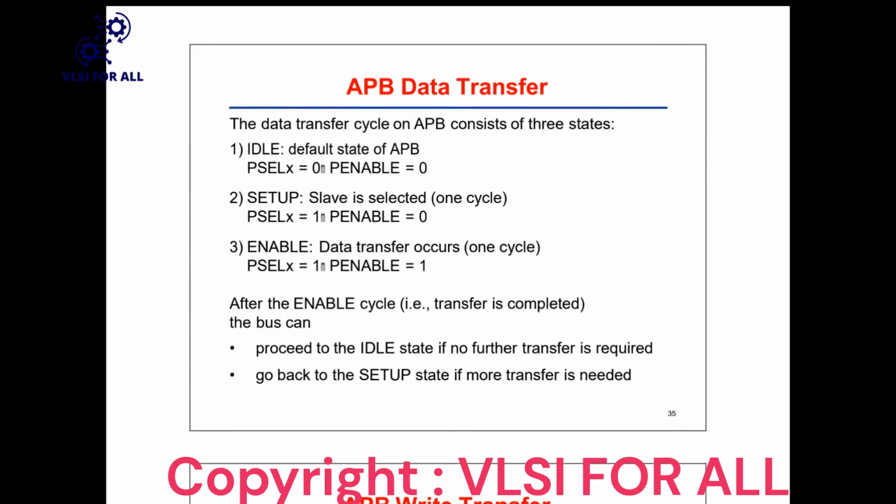Till then, whatever control signals were driven in the setup phase will be extended as they are. Their status won't change. But write data is not yet driven, because we don't know whether the slave is ready or not. When the slave is ready, only then will write data be driven. Till then, the control signals already driven in the setup state will be retained, or extended as they are. And then, let's say our slave is now ready, so we will do the required transaction.